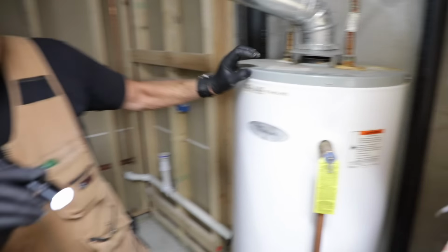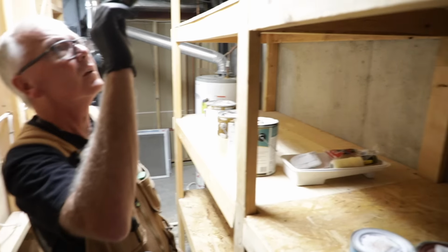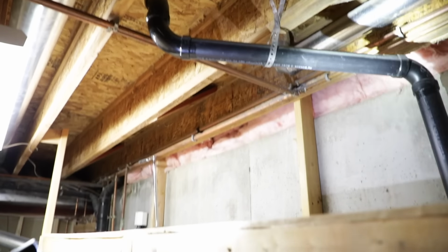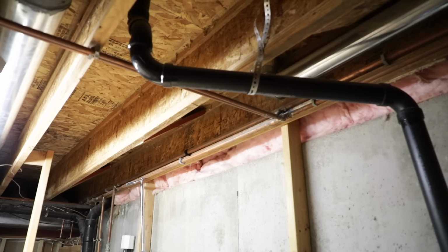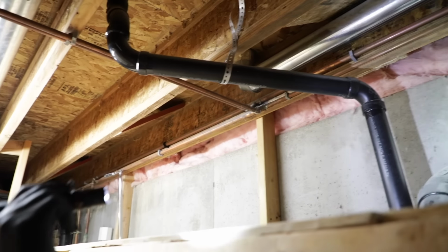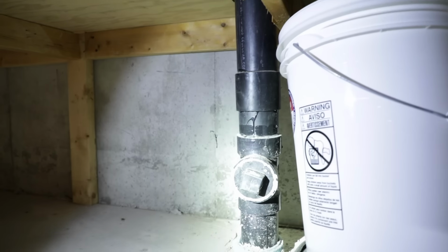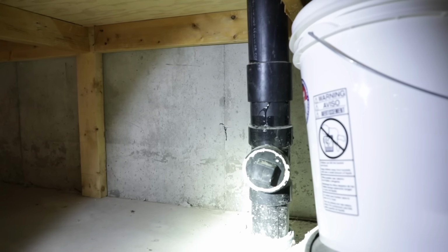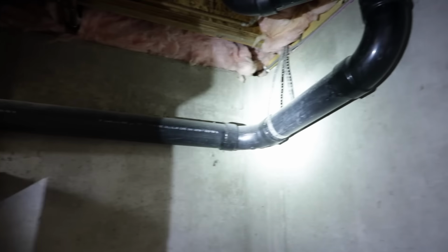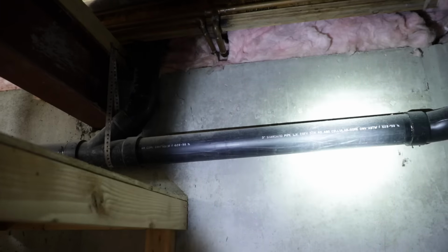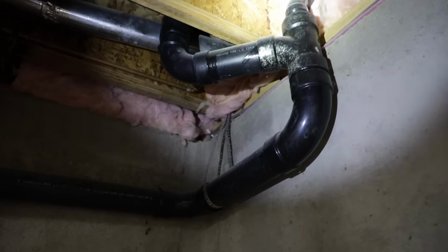We'll go back. There's a little bit more behind us here. They do have strapping on these pipes, which is good. They're being supported. Just look for any leaks. Got another clean out here. This is another major line going underneath the concrete. We got a little bit more behind us here. Everything looks pretty good. It's all secure. I don't see any leaks.